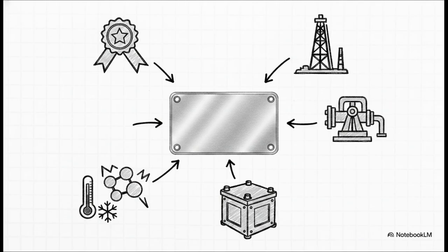Let's read this like an engineer and break it down character by character. Ex means it's certified. II 2G tells us it's for above-ground use, specifically in a Zone 1 gas atmosphere. Ex d proves it uses that flame-proof containment method we just talked about. IIC means it can handle the most easily ignited gases, and T6 means its surface will never get hotter than a very cool 85 degrees Celsius. Listen, if this nameplate doesn't perfectly match the hazardous area drawing, it cannot be installed, period.